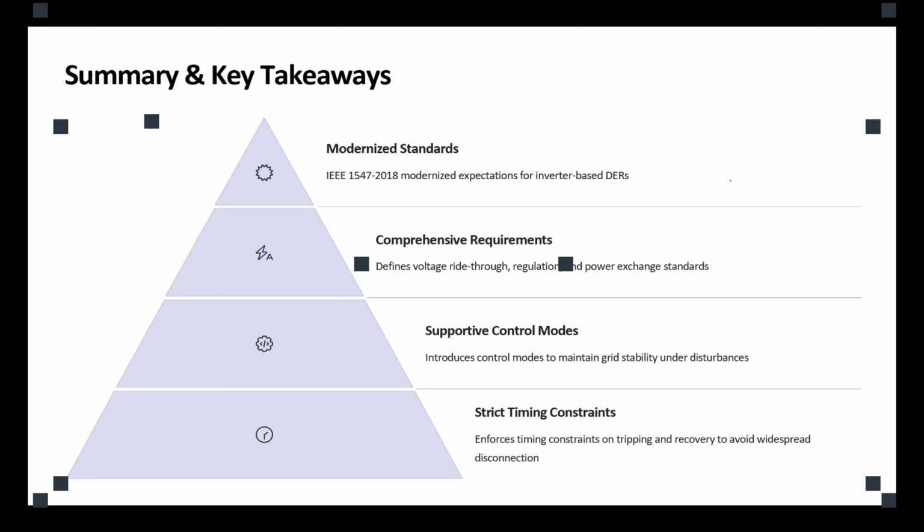Okay, since your assignment 4 is based on fault ride-through analysis, I added a step-by-step guideline. I posted that in Canvas: how you can change your current control system in order to be able to do fault ride-through. So you have your droop control. How can I change it so it would be able to do fault ride-through?